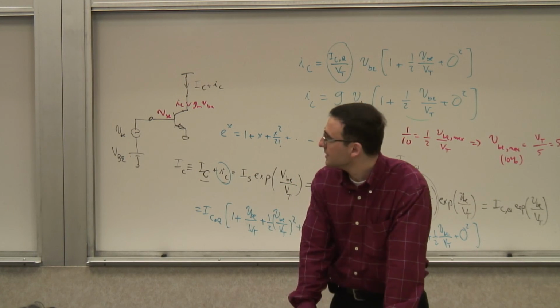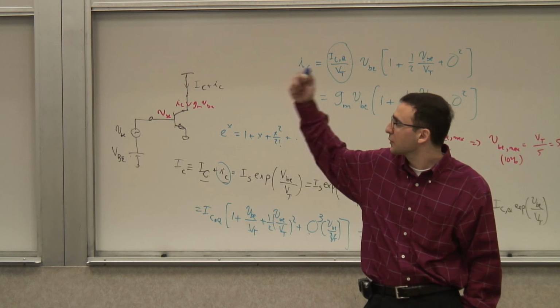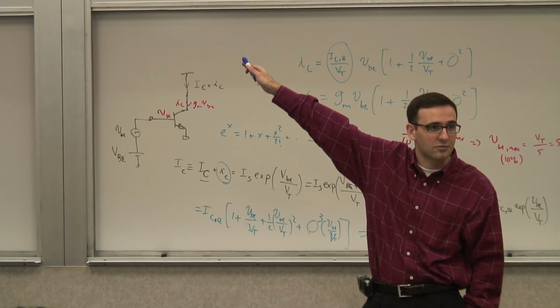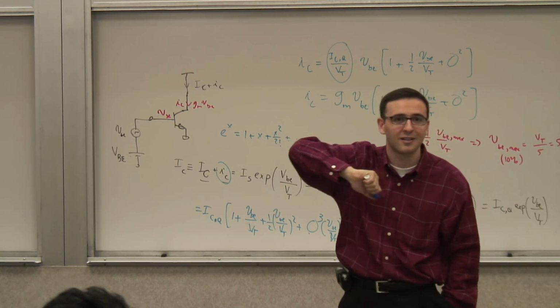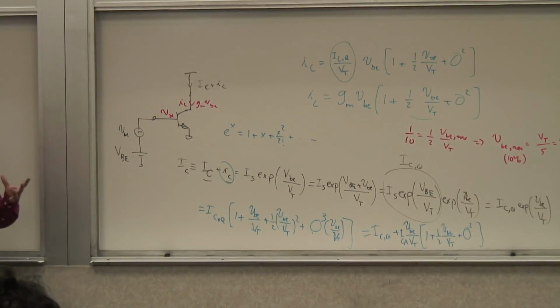Right. No, this is an additional tool to help you with AC calculations. It also allows you to think about it. But you can never use it for DC operating point calculation. Never ever calculate the quiescent current with the small signal model. You're guaranteed to be wrong if you do that. It's only a perturbation method. I can't be more emphatic.